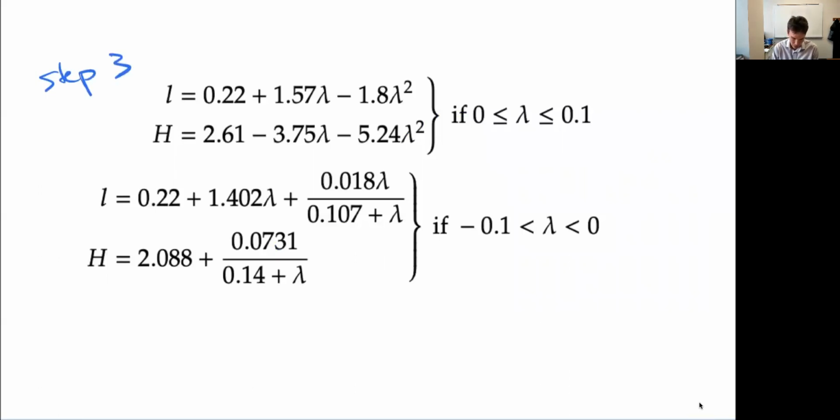We're also going to say that if lambda is less than minus 0.1, so that goes below this fit, remember, that's bad. That means our boundary layer is becoming more vertical at the wall, so our slope is becoming 0 in terms of du/dy. It's about to separate. So that's going to be an indication of separation or transition, and for our purposes in our homework, we're going to use transition.